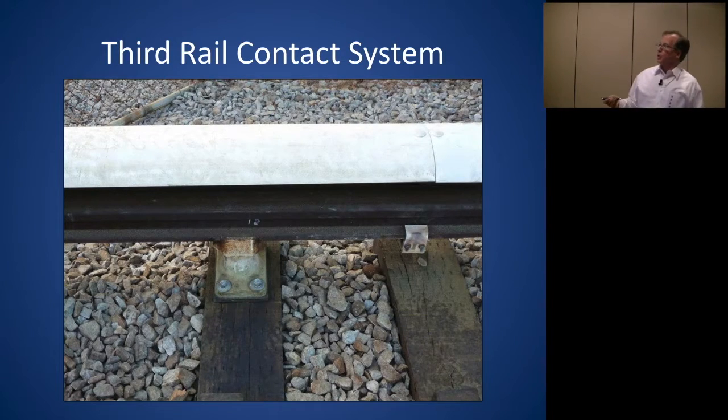This is a common third rail type system. This is either porcelain or fiberglass. It's an insulator. It's setting up off the ground a good 6 inches. What is it, 6 or 8 inches? Something like that. Those are pretty rugged. It's pretty rare for the positive to leak because it's very high resistance. I mean, a track-to-earth resistance is somewhere in the neighborhood of 500 ohms per 1,000 track feet. A contact rail or an overhead contact system is more like 40 megaohms, kind of, in relative terms.